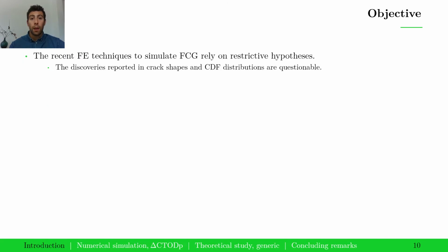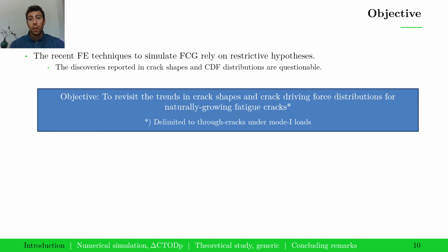So, to sum up, we see that most of the present finite element techniques to simulate fatigue crack growth still rely on restrictive hypotheses, which questions the reported trends. Therefore, the objective of this work is to revisit the trends in crack shapes and crack driving force distributions for naturally growing fatigue cracks. For the time being, we delimit this study to through cracks under mode 1 loads.